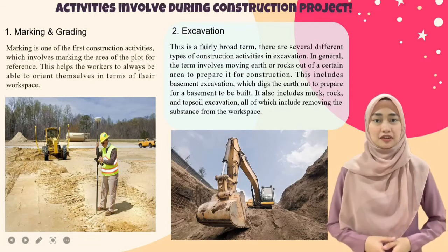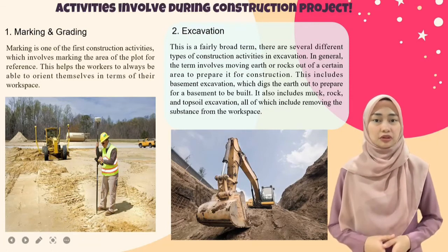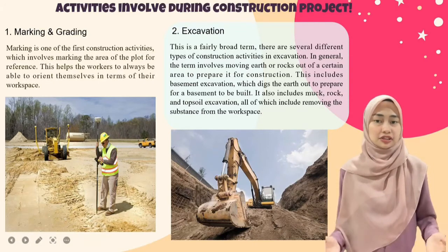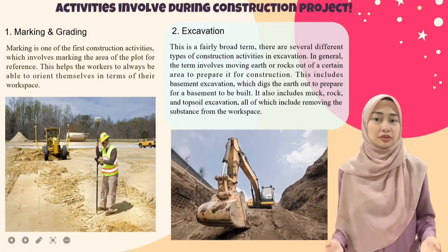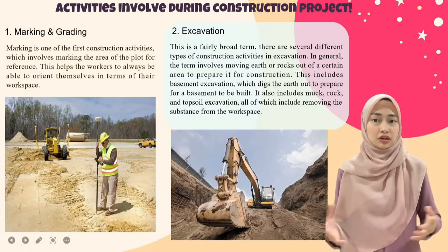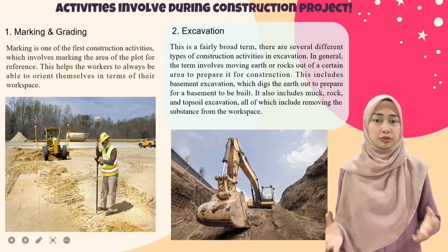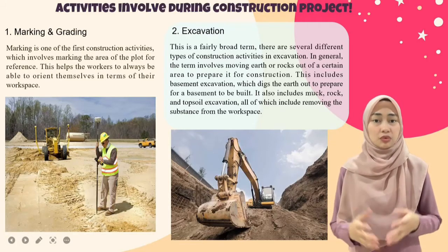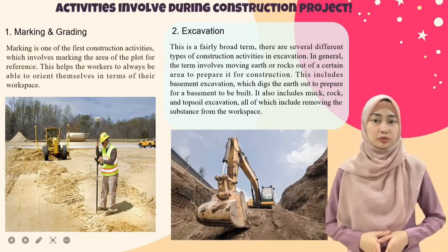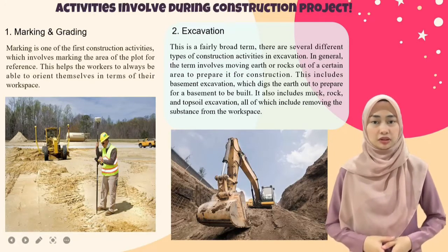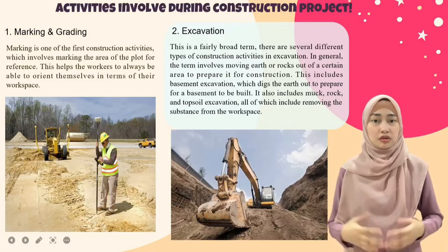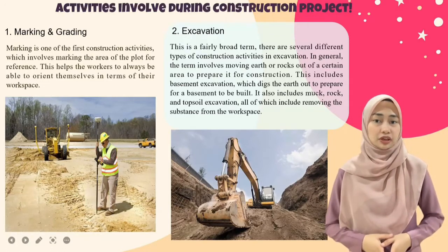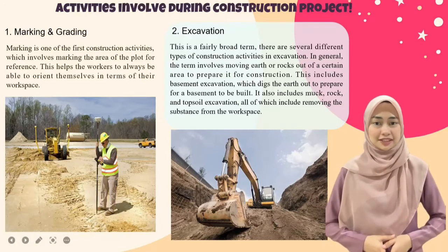Second is excavation. This is a fairly broad term. There are several different types of construction activities in excavation. In general, the term involves moving earth or rocks out of a certain area to prepare it for construction. This includes basement excavation, which digs the earth out to prepare for a basement to be built. It also includes mud, rock, and topsoil excavation, all of which include removing the substance from the workspace.